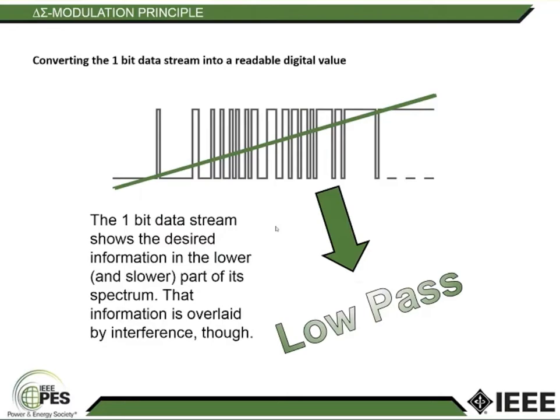So the simplest form of a low-pass filter is the mean average, because the frequency is obviously reduced by averaging the values. There's more complex and accurate forms of low-pass filters around though, sinc filters. And we will have a closer look at the behavior of those sinc filters now.